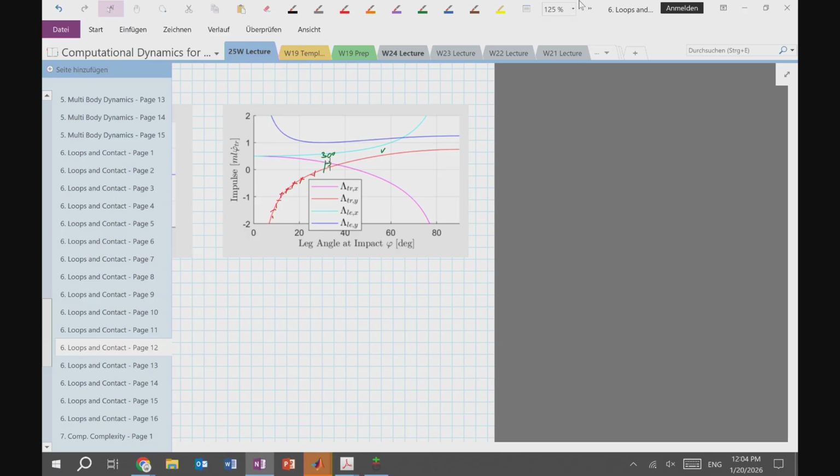I can also try to explain to you what the mechanism is. It has to do with this contact space mass matrix lambda. To reason about this, think of a rod. It has its center of mass somewhere in the middle, has a mass, and also has some inertia, let's call it J, which is comparatively small against the mass. So this is made from styrofoam, and then there's a heavy lead core in there. And it's sitting on a plane. Gravity doesn't play a role. And now I'm going to hit it with an impulse.